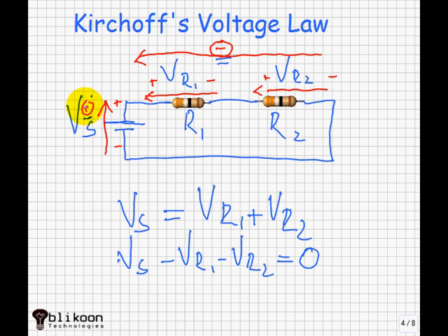Plus means that the voltage source provides energy, and these guys come to consume it. Another way to write KVL is to say that the sum of all the voltages in the loop equals 0. But when you are making your sums, you make Vrs negative and you make Vs positive. We're going to see how we can use this law quickly in the next slide.